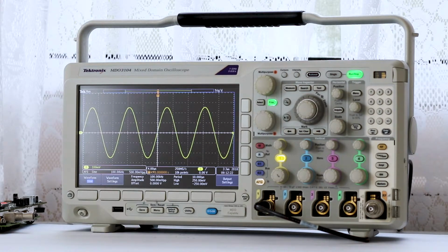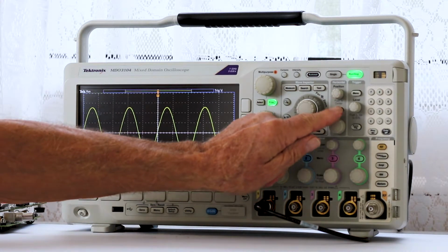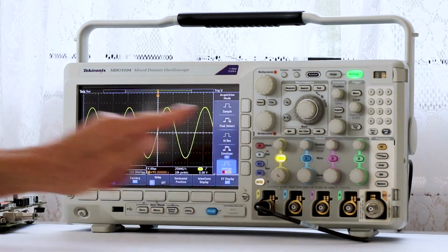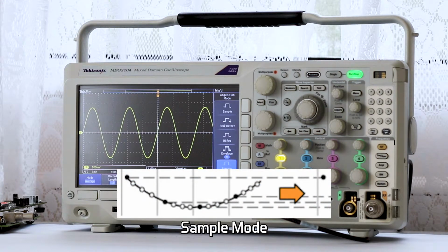When Acquire is pressed, the acquisition menu appears across the bottom of the screen. The first menu selection is Mode, and the default mode is Sample, which retains the first sample point from each acquisition interval.